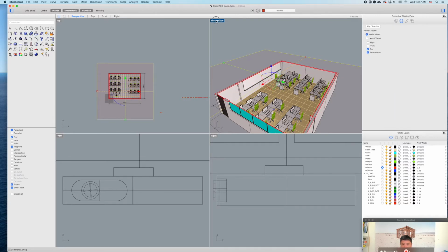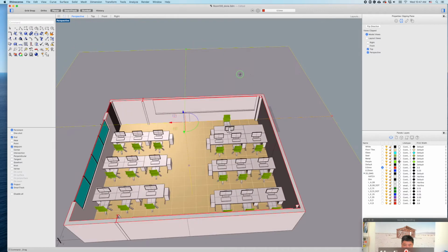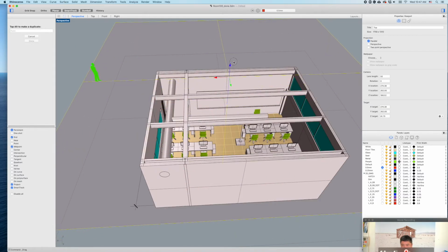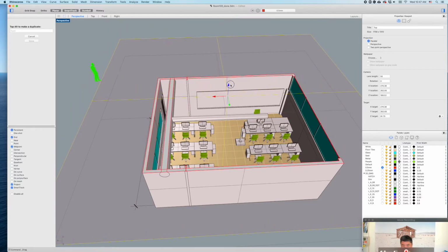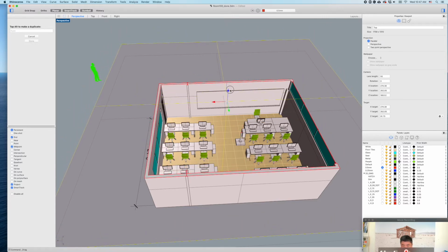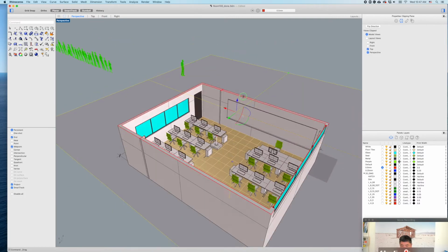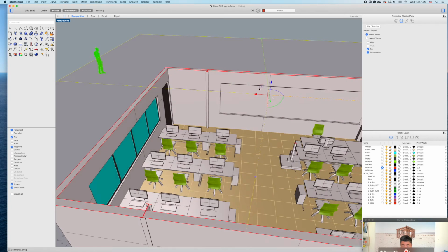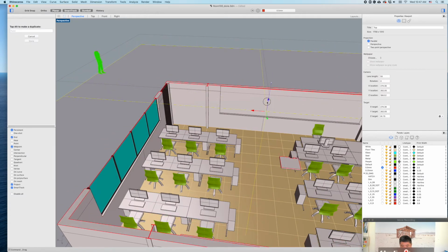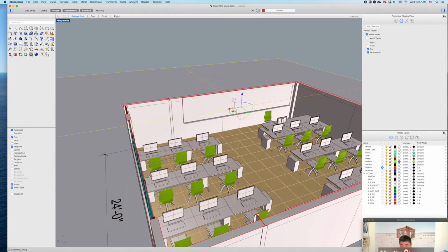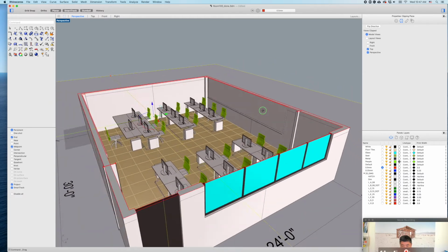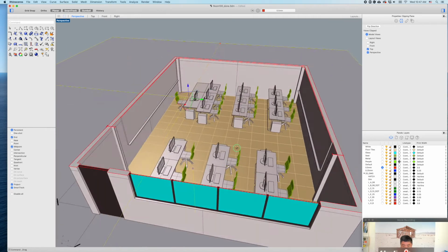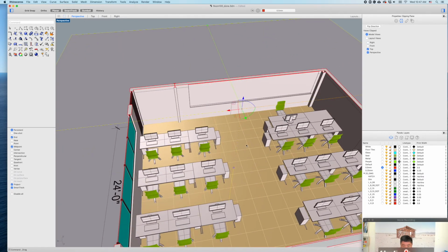Okay, so in this case, we are cutting through this room, and typically the convention is around 4 feet from the ground, and it actually varies. In this case, we would like to cut through this window. This window and this window don't actually overlap, so we have to pick one side. So this is a pretty good height for this. It's around human eye level, and it cuts through most of it.